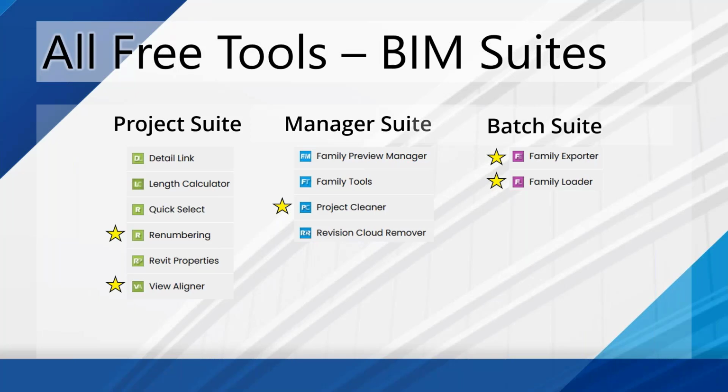And I want various things turned off. So no reference planes, no dimensions, no levels or grids, or if any of that stuff shows up. All that stuff will be turned off, and you'll just see a rendered image of that family, and that'll be your thumbnail. Pretty slick.